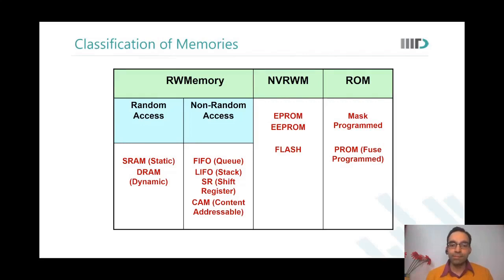So after I have fabricated a particular lot, I'm doing an initial kind of step to make it operable. After the fabrication has happened, I estimate what lot the device is at. Now I simply fix that, okay, if it is a fast lot, then the leakage is going to be very high. So I have to lower the voltage of operation so that leakage comes under control. Because it's already fast, performance is not an issue for me. So I will trim. I will say that, okay, instead of operating at 1.3 volts, operate the chip at 1.26 volts. And this calibration will be done using these PROMs.